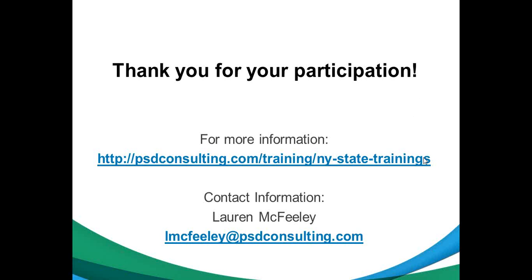Good question. Any difference between retuning and retrocommissioning, or is this a subset? Yeah, there is a distinction. It's a really great question. Retuning, at least this large building retuning, is very focused on using the data from the building automation system and making recommendations for changing set points in the building automation system. If something is really out of whack and it doesn't make sense with the settings, you might go investigate in the field to find, wow, the dampers on the air economizer are stuck, and they're stuck open, closed, or in one fixed position. And then in that case, the maintenance staff may correct that, or there's a faulty sensor and correct that.